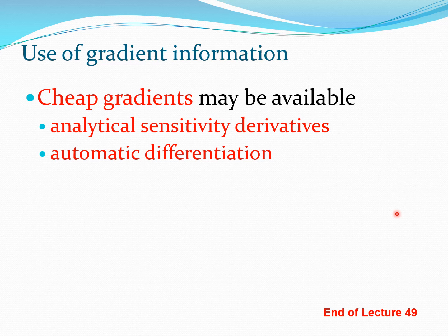So if you feel that your problem is somewhat complicated and polynomial functions are not sufficient, you may decide to add a trigonometric series to this particular function. And in those cases you may need more and more points to sample the design space so you can get the regression parameters correctly. And in all those kind of situations it becomes useful to use one of these techniques such as progressive lattice design or probabilistic points or gradient based points.